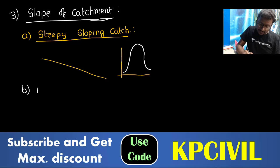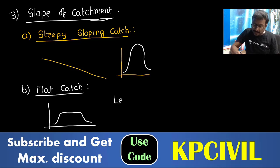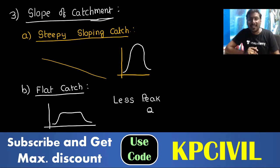Flat catchments, normal slope, will get less, no? Peak discharge is less for flat catchments, like this. So less peak discharge. Flat catchments will carry less peak discharge. So who is carrying more peak discharge? Steeply sloping surfaces. A catchment with a steeply sloping surface will carry high peak discharge when compared with a flat catchment, which has less peak discharge.